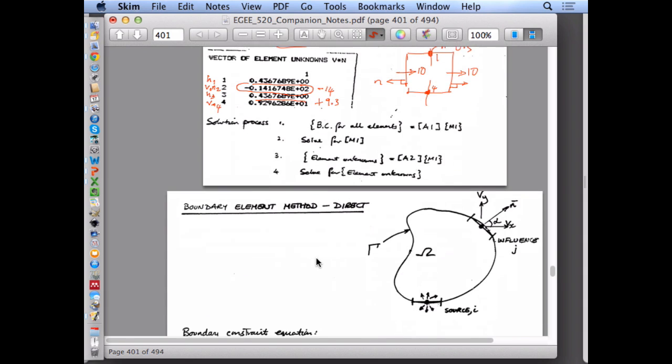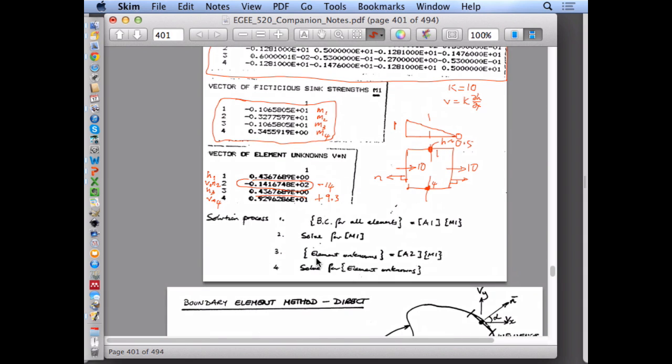And so I kind of enjoy that because it really is very simple. I mean, I won't repeat it, but the technique is very simple. You just apply sources of some description to be able to satisfy the boundary conditions. If you're solving a solid mechanics problem, then the Green's functions you're applying are for a crack opening, where you can calculate the stresses and displacements away from that crack, and you have those cracks distributed around the boundary to be able to satisfy the boundary condition.